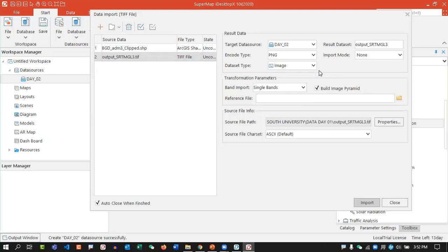as we want to process this dataset to prepare some catchments, showing how to delineate the watershed, and also map the stream order of this area, and also some other mapping processes. So we will import this dataset as a raster dataset, and I am naming this one SRTM DEM, digital elevation model data.